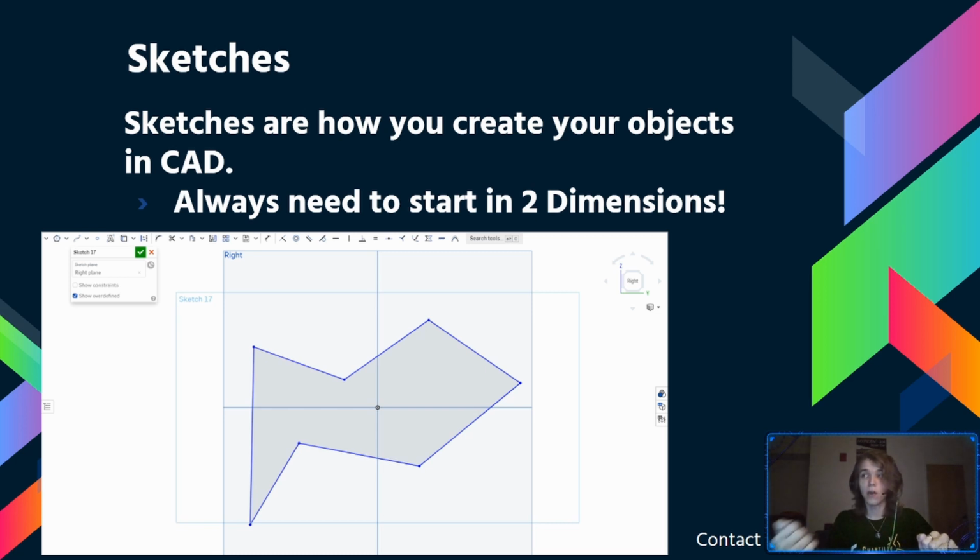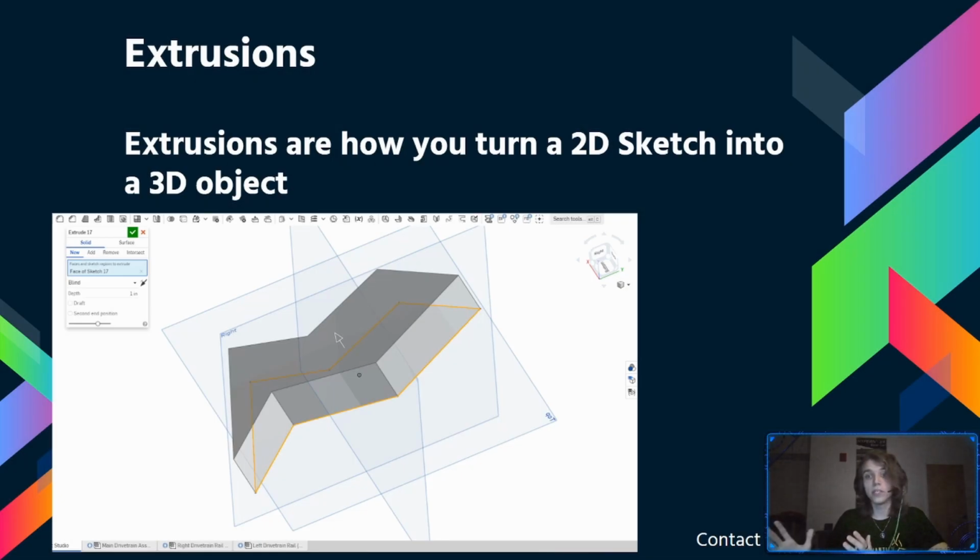So whenever you sit down on your CAD program at your computer and you want to make something, you always start with a sketch. Sketches are just two-dimensional drawings of what you want your final piece to look like. That is always the first step. So if you don't know what you're doing, think, do I have to start with a sketch? Once you have these two-dimensional sketches finished, you can do something we call an extrude, which then pulls that two-dimensional object out into the third dimension. And so it's through that two-step process of sketching then extruding that you can actually make your three-dimensional objects.